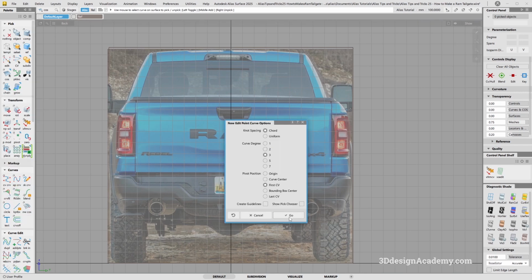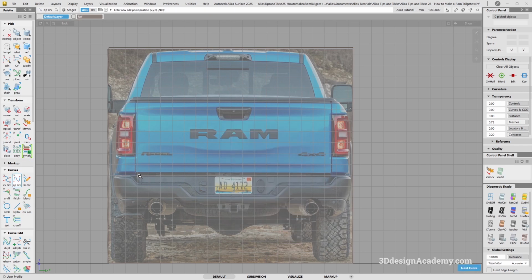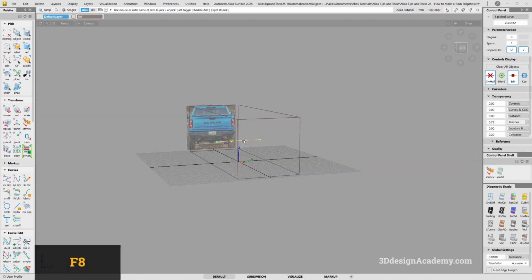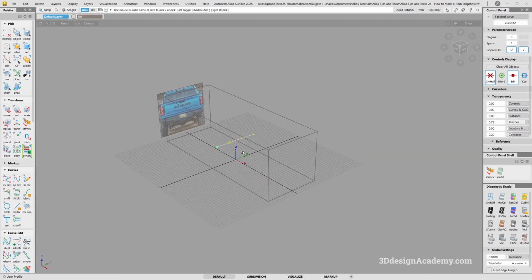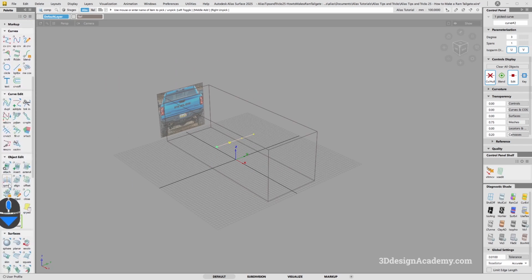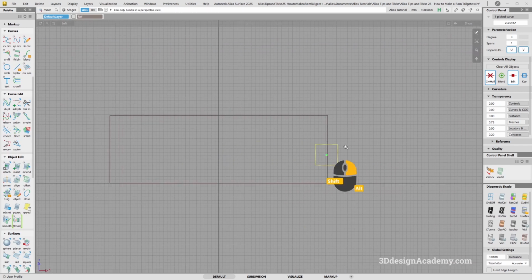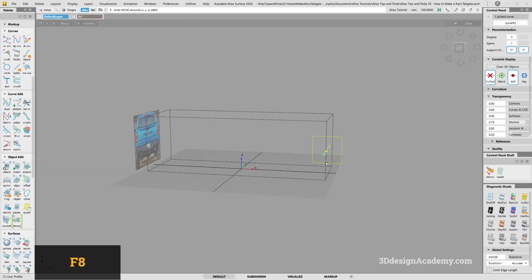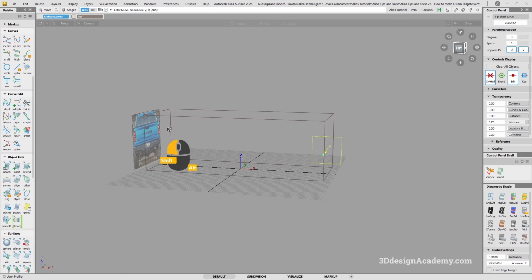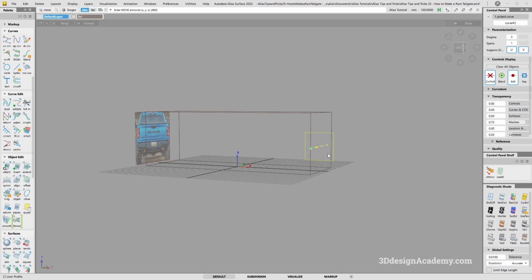Okay, so the first thing I'm going to do is grab a degree 3 curve and strike it from here to here like this. And of course, because it's going through the center, as anything that is going through the center should be, I'm going to just go ahead and turn on symmetry like this. Now, of course, the tailgate is going to live somewhere on the rear, so I'm just going to put it there. Because I set this as the primary, the feature that you see on the bottom, I'm going to just stop it a little bit short of the end.